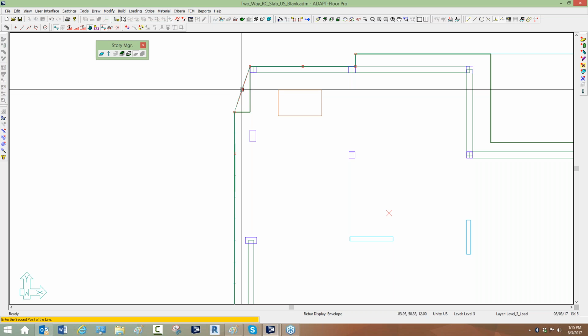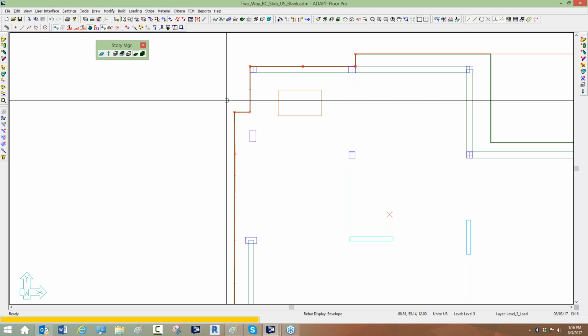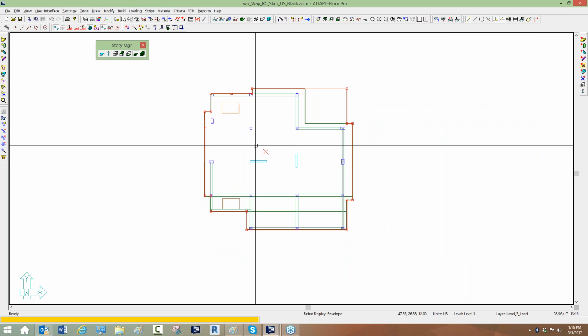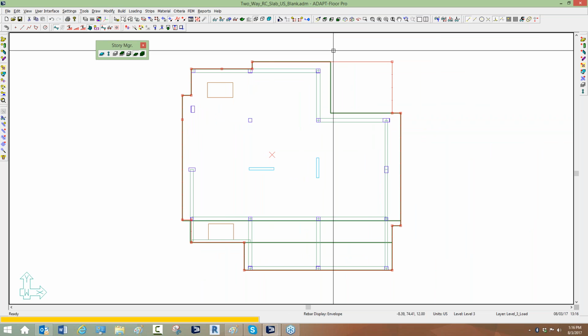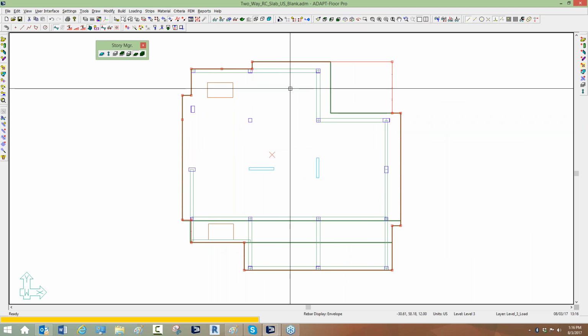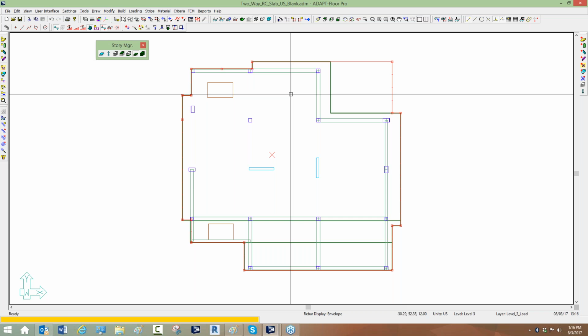So it's almost a guessing game. It actually depends on the sequence of nodes that are assigned to the slab. So a lot of times if it inserts it on the wrong span, you just insert another versus going and determining what the numbers are for those points. But anyway, you can move that point now to the corner if you want to have a perfectly aligned loading arrangement relative to the slab. So it's not required, but you can do that if you need to.